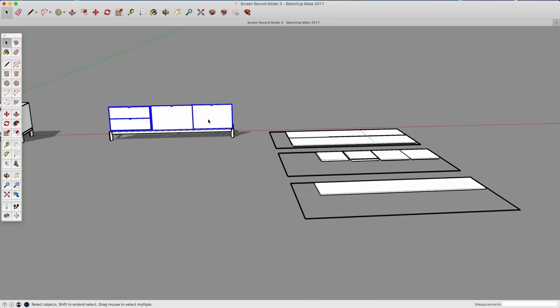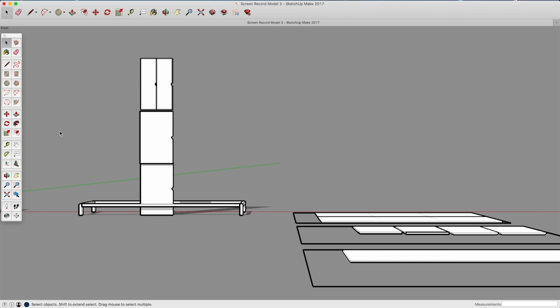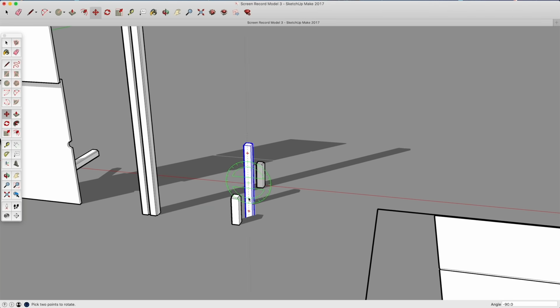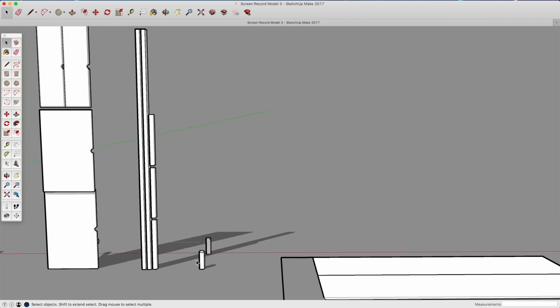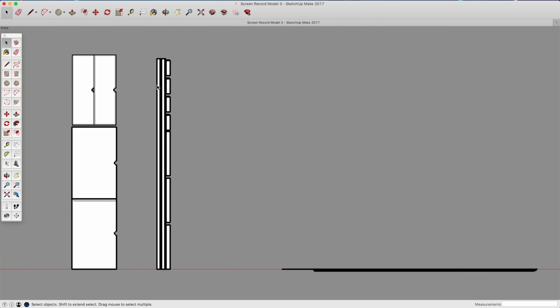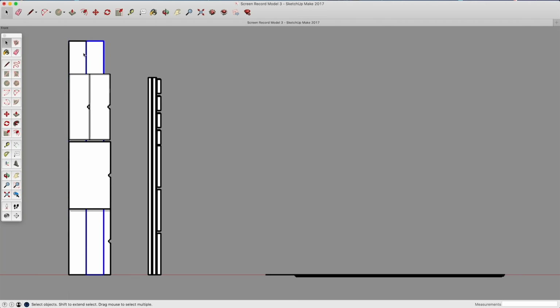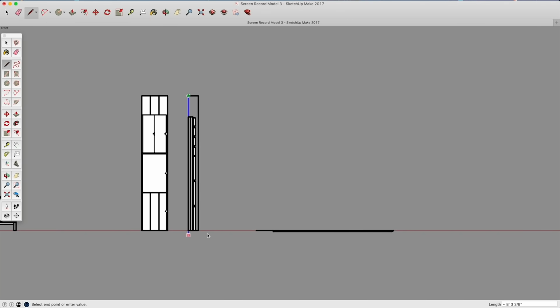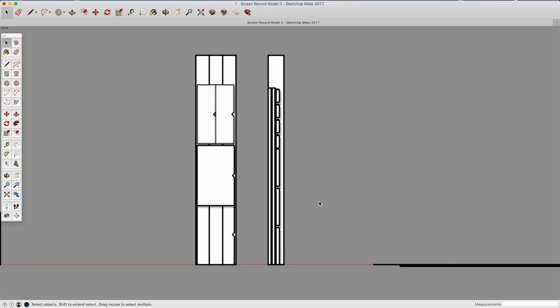And then I'm going to group together my hardwood pieces of similar thicknesses. Based on that, I can see that I'd want 3 pieces of 4/4 hardwood material that's at least 6 inches wide and 8 feet long. And I'd need 1 piece of 8/4 hardwood that's 6 inches wide and 8 feet long.